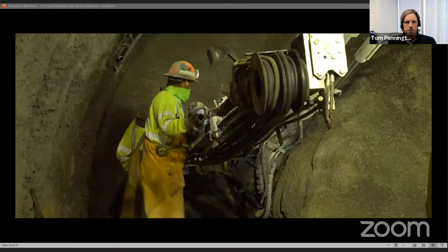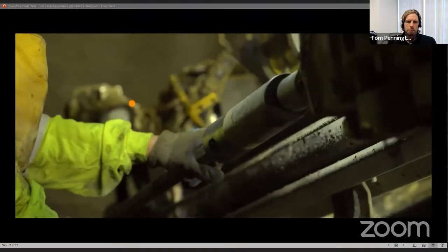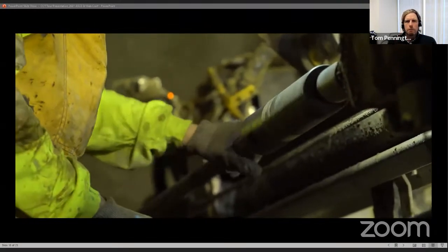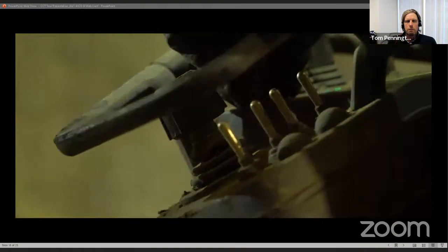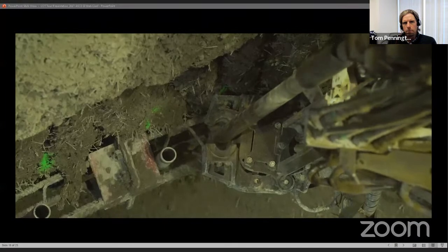These pipes are much less stiff and therefore cannot carry the higher loads of the larger canopy pipes. However, since they are shorter, they more easily allow for changes in the tunnel alignment. They are drilled with a drill jumbo using a smaller crew and are thus more economical.